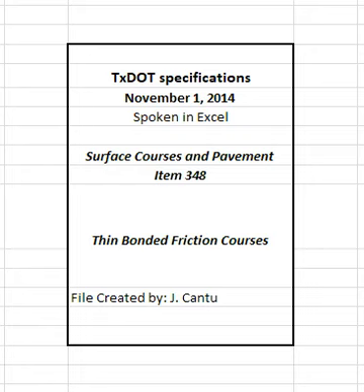4.9.1 Referee Testing. The construction division is the referee laboratory. The contractor may request referee testing if the differences between contractor and engineer test results exceed the operational tolerances shown in Table 9 and the differences cannot be resolved. The contractor may also request referee testing if the engineer's test results require suspension of production and the contractor's test results are within specification limits. Make the request within 5 working days after receiving test results and cores from the engineer.